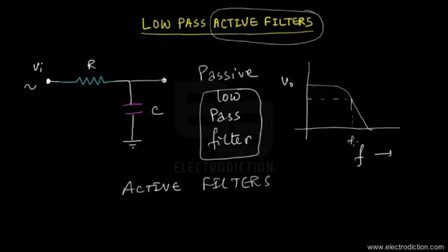Let's say this is our cutoff frequency, termed FH. What this circuit basically does is let the frequencies below the upper cutoff frequency, FH, appear at its output as the output voltage. Those frequency signals which lie below its upper cutoff frequency are passed on to its output unattenuated, while those above FH are attenuated by the circuit itself, as we described in the previous tutorial.